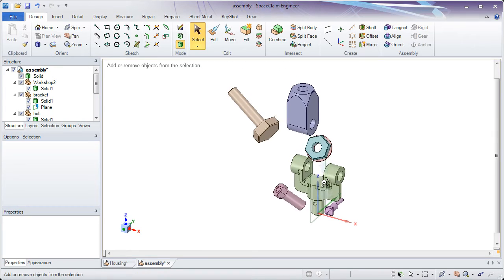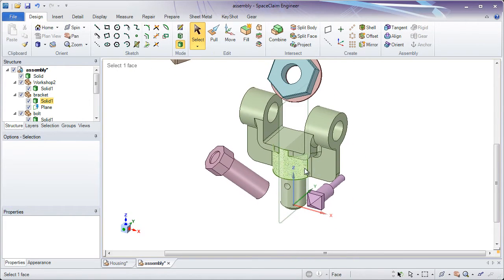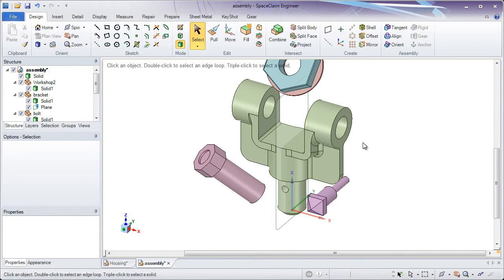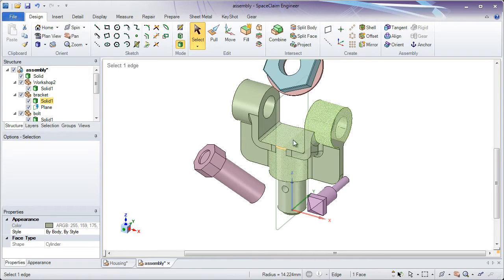When we're assembling components together to make a static assembly or a dynamic mechanism, we'll want to start with the bottom up. Think of this as a Mr. Potato model. Start with the feet being static and start to assemble things on top of that to build out the model. So whichever part isn't going to be moved should be the part that's anchored. You'll notice in the bottom right-hand corner of the assembly group we have an anchor button. Clicking any face on the part and clicking anchor automatically locks that part down.